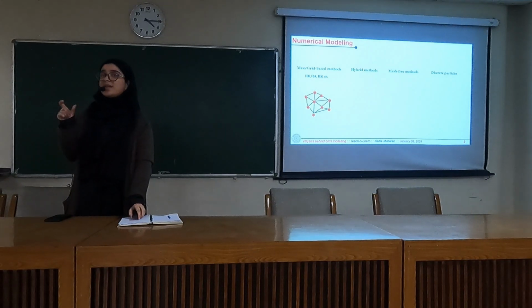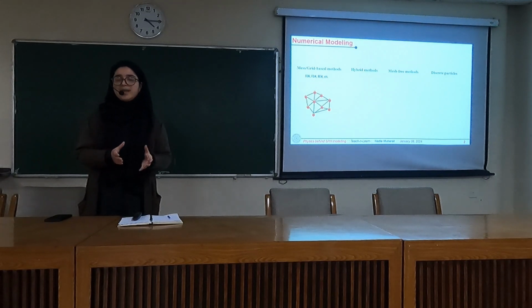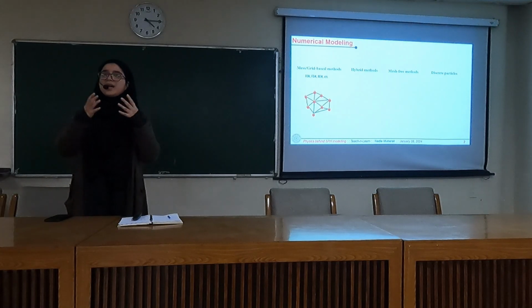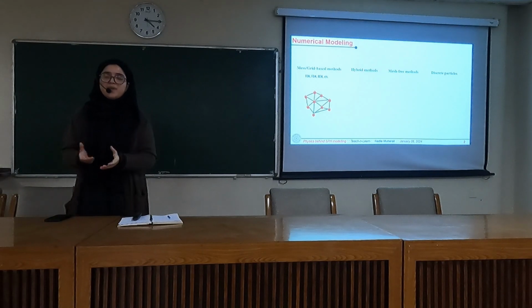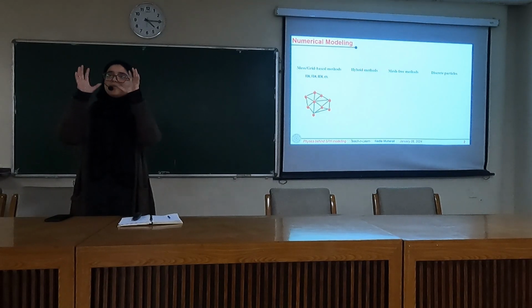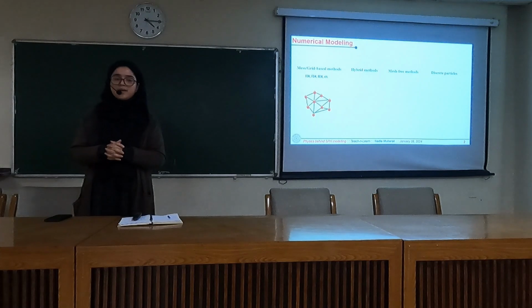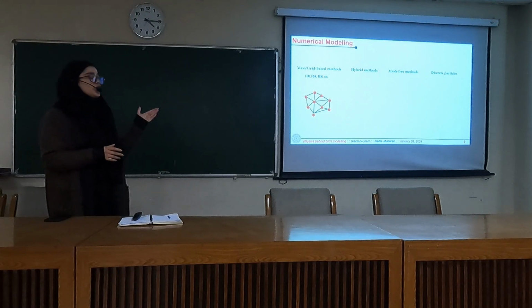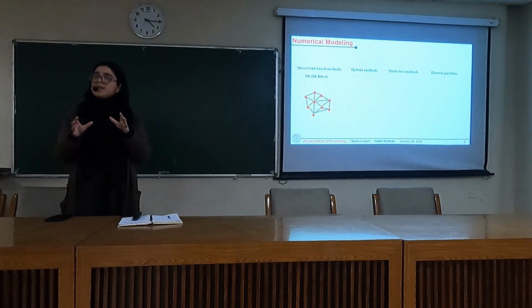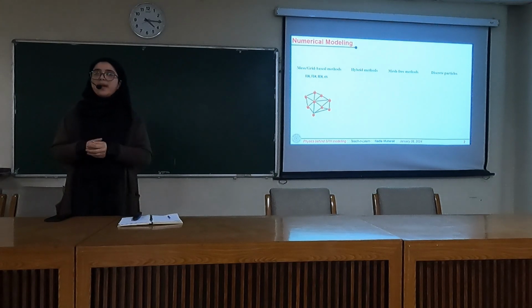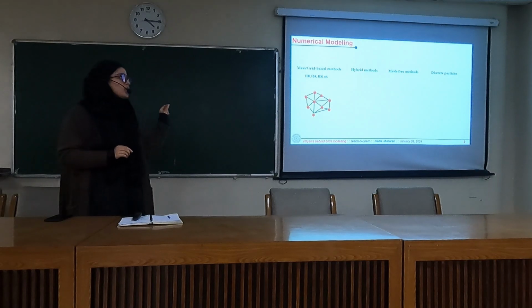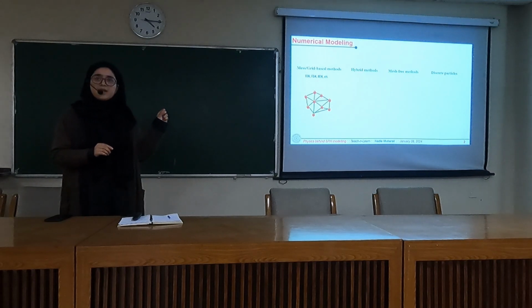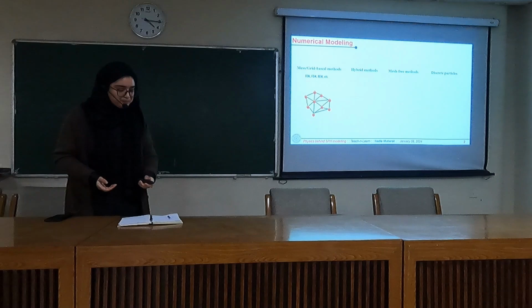So discretization is a very important part of numerical modeling because otherwise we have infinite data points. That means an infinite amount of data. So it's important that we discretize the model first. In grid-based or mesh-based methods, the discretization is done using a mesh, and then the domain is discretized into small elements, and it's the nodes where the information is collected, or calculated.